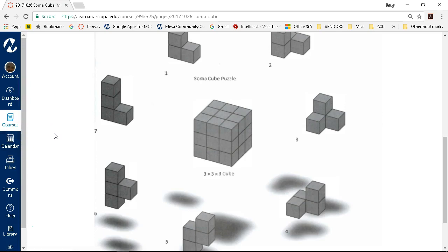One of the things that I think has been a limitation is that I've talked a lot about subassemblies, but we haven't ever created any real in-depth subassemblies. So going through 5.2 and generating the 16 or 17 parts, either as individual parts or as configurations with 3 or 4 parts, we're going to have some strategy to build our geometry and put it into an assembly. The only thing that really makes a subassembly is whether it is embedded in another assembly or is standalone.